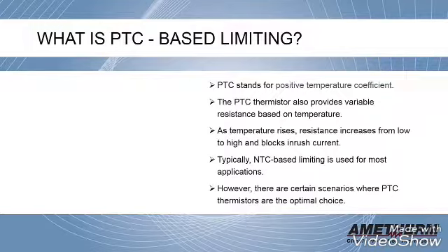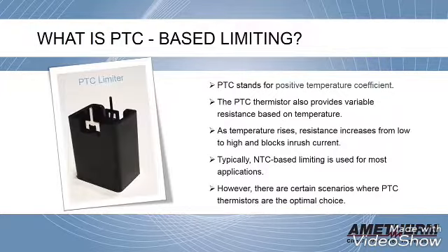What is PTC base limiting? PTC stands for positive temperature coefficient. The PTC thermistor also provides variable resistance based on temperature. As temperature rises, resistance increases from low to high and blocks inrush current. Typically, NTC base limiting is used for most applications. However, there are certain scenarios where PTC thermistors are the optimal choice.